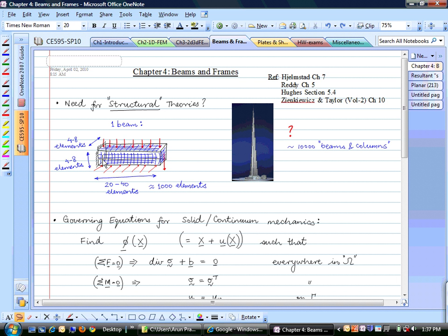If you want to analyze this with continuum finite elements, we saw that when you started to use 4 to 8 elements along the width and the depth, you started to get a reasonable deflection. When you used a 4-layer or an 8-layer element or more, you started to get the real displacement; it started to converge.